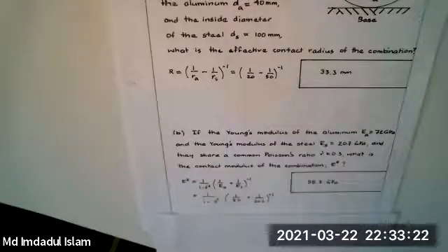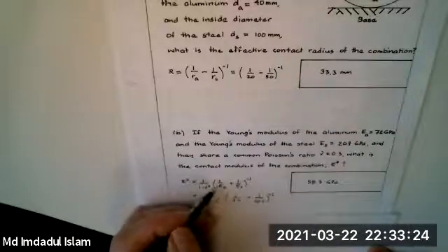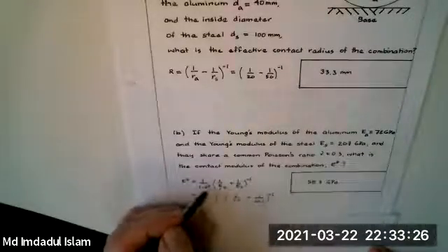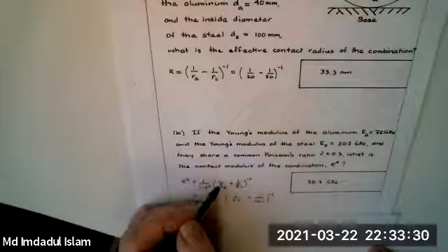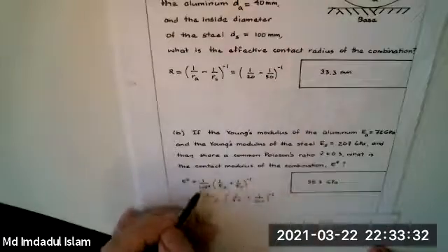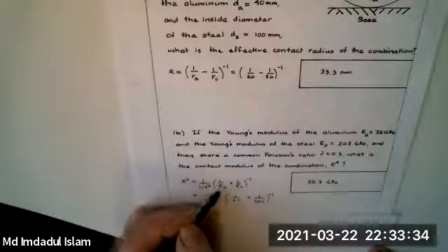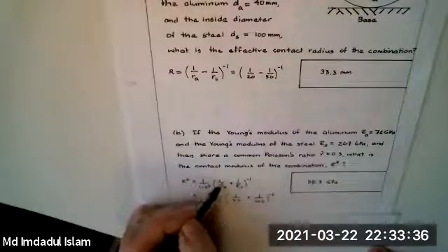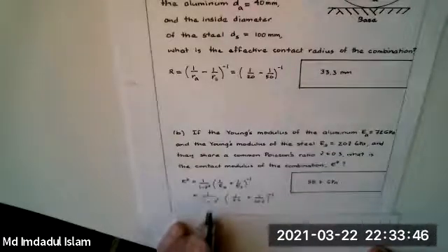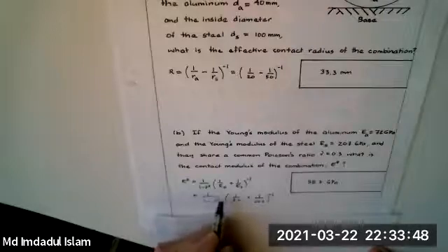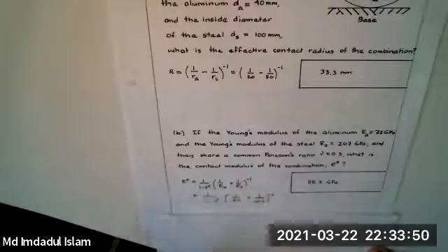The Young's modulus, you could have put, it's the sum of the reciprocal of the contact moduli. The contact moduli have a 1 minus nu squared up there. Since it's up there both and the minus 1, I just put it outside, but you could put it up there, it doesn't matter. You could even put 1 minus nu a squared plus 1 minus nu s squared. Either way, it doesn't matter. That's a Poisson's ratio effect. It makes E star bigger, okay? Makes it a bit stiffer because of pushing in from the side.